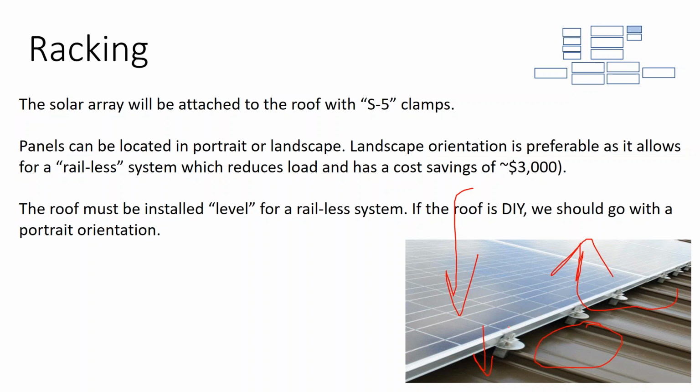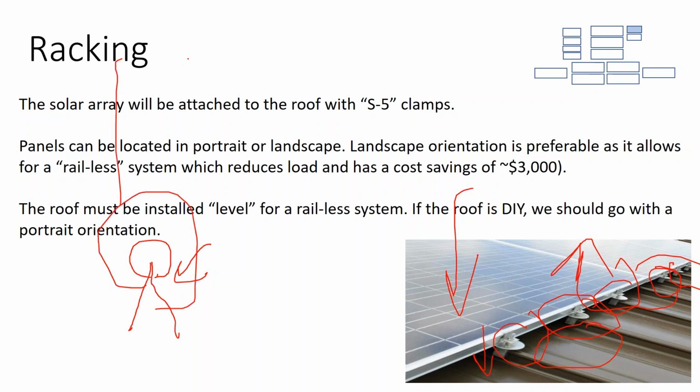It's a pain in the butt to go and install these clips along every single seam, especially if you go with the cheaper kind of metal roofing system. Our standing seam metal rooftop was actually a triangular crimp, and so we had to take a crimp tool or a clamping wrench and push the triangular standing seam into a straighter triangle so that our clip would actually fit onto it.